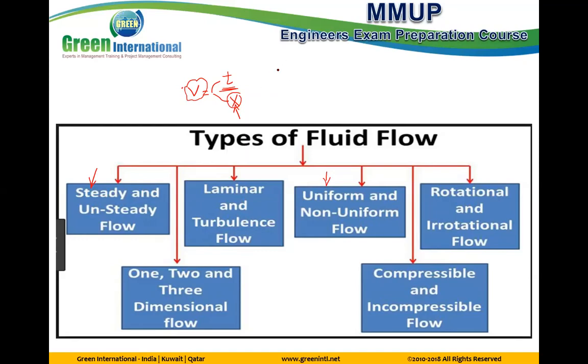It means if we study the velocity with time, the other parameter should be kept constant. It means if we have a flow in a pipe like this, for example, I study the flow at a certain x, constant, not a changing x, but I study what happens to the velocity with time: at time t1, at time t2, at time t3, and so on. But still we study all of this at the same position. This classification is related to steady and unsteady flow.